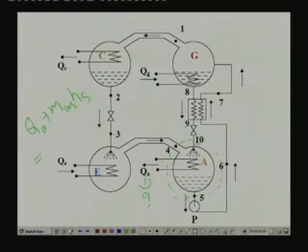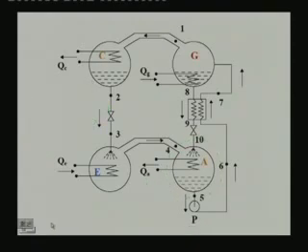So, energy is coming in by way of mass flows. So, energy coming in is m into H1, this is nothing but the energy contained in the refrigerant plus m strong solution into H10. Okay. So, this is the energy balance for the absorber. So, from this equation we can find out QA, because we know all these mass flow rates and enthalpies. Okay.